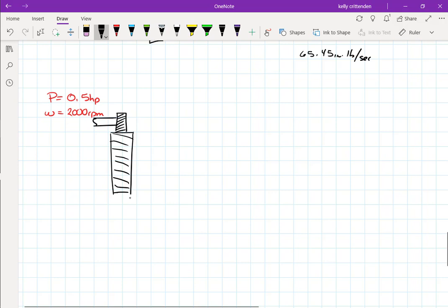All right, so there's our pinion with 10 teeth. Sometimes you're not given the number of teeth, you're given the diameter of these gears. It works the same way. The diameter is directly proportional to the number of teeth. The teeth on the pinion and the gear have to mesh with one another, so they're actually the same size. So it doesn't matter if you're given teeth or diameter for the gears. It works the same way.